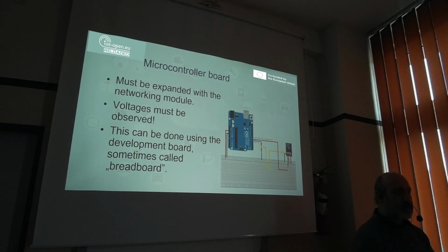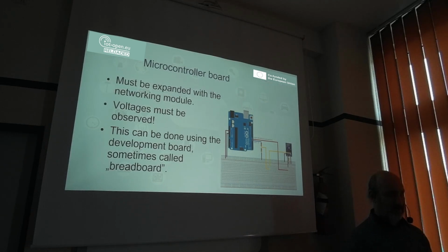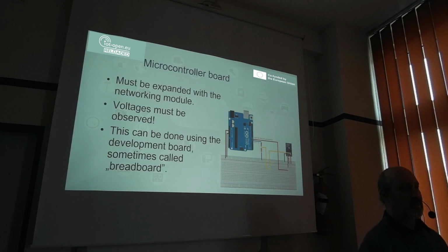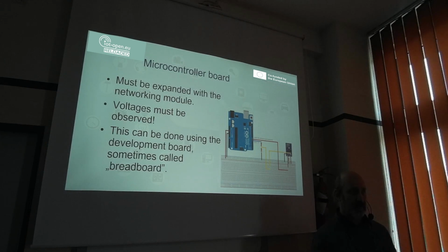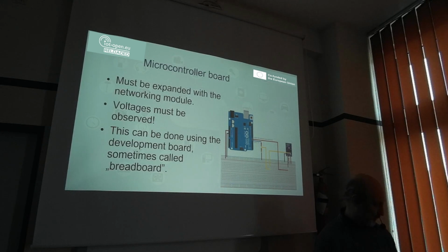So these voltages must be observed to not burn something. If you provide too high a voltage to a board that doesn't accept higher voltage, you can damage it. So the voltages always must be observed if you connect different elements. This can be done using some experimental boards like this white board here, sometimes called a breadboard.